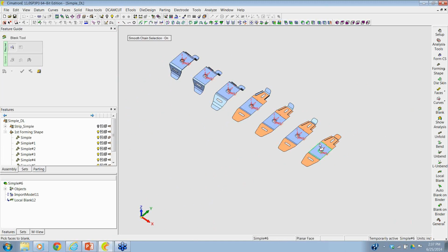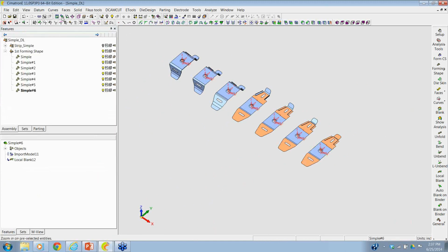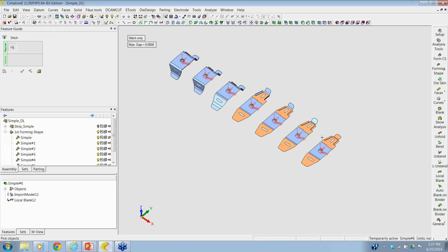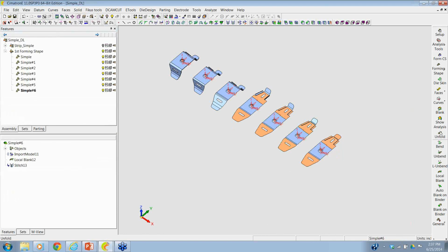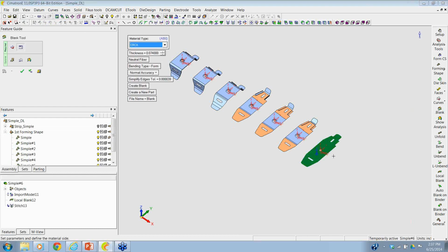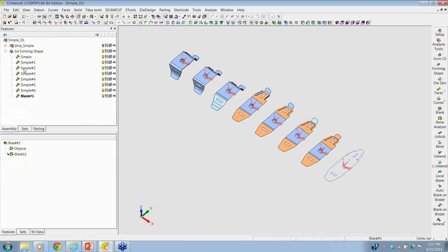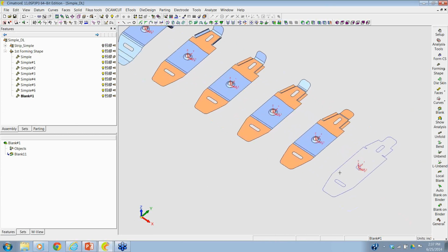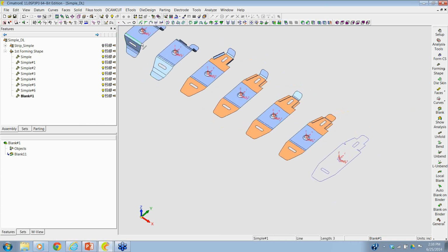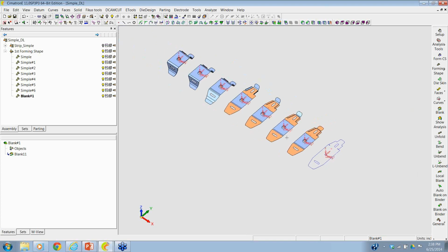Let's now grab our perimeter, our 2D shape. One more thing, please. Make sure this is all one coherent sheet, and then we'll grab the perimeter of this part. And that'll be our unfolded blank then. Because I have progressively worked through each operation of the unfold, this blank that I'm resulted with now is going to be more accurate than when I first hit the part and did the blank. That part originally was like putting a foot on it, smushing it down, going to flat, right from center. By controlling each unbend, I've much more imitated what the process would be like.